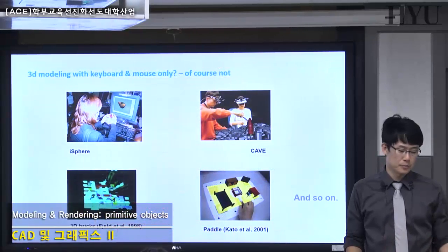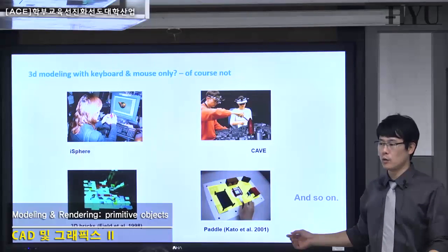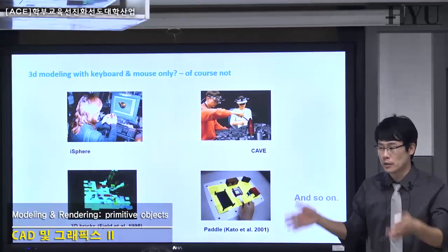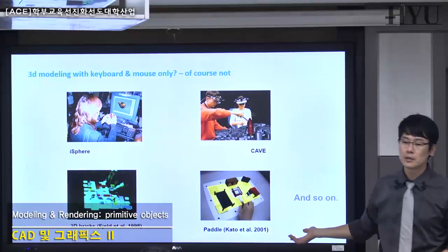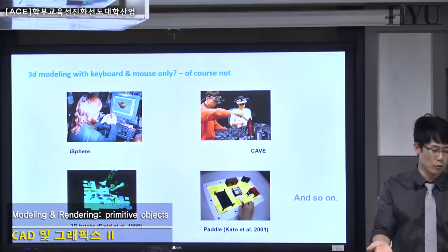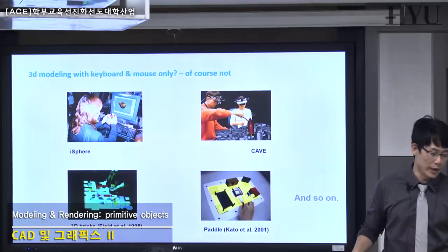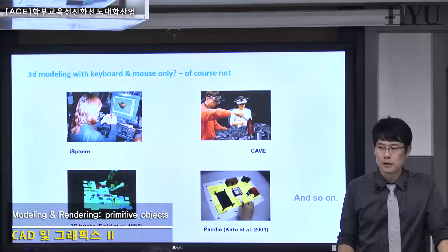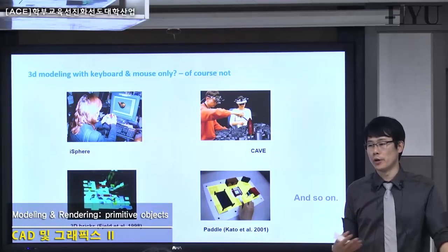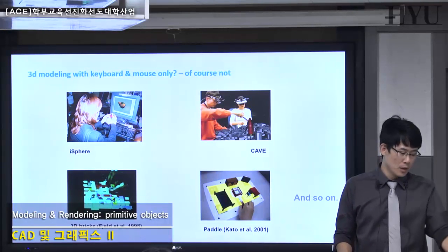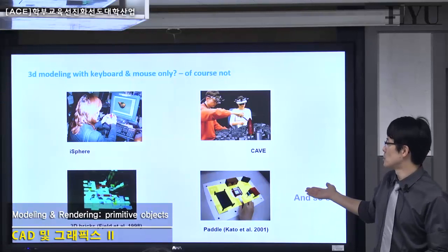In 3D graphics, anyhow, you have to create something like this, even if it's simple, and you have to modify this geometry. How to modify? What to modify? Subcomponents, okay? Not just controlling this one. You can control this box, but actually we can control vertex, edge, border, polygon, element. All they are subcomponents of this box.